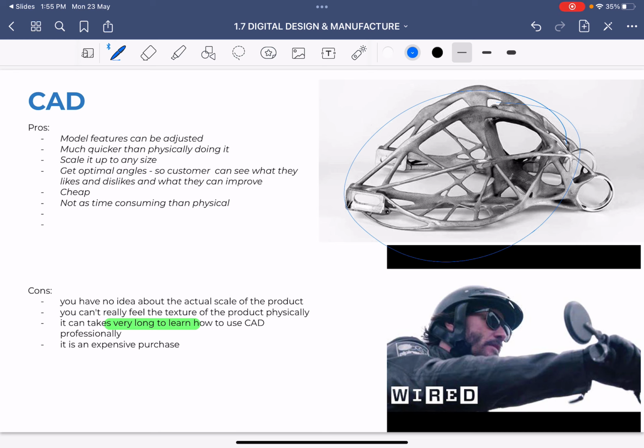So it's not easy, and it has a steep learning curve. However, there are many pros to CAD. One of the main things is adjustability or editability. CAD can easily change parts of the design, say on this wishbone here, and all these structures can be altered and then they'll update. So if the designer wants to increase the thickness of that section there, suddenly all of these parts here would update accordingly. Whereas if you were hand modeling or sketching, you'd have to redraw the entire thing.